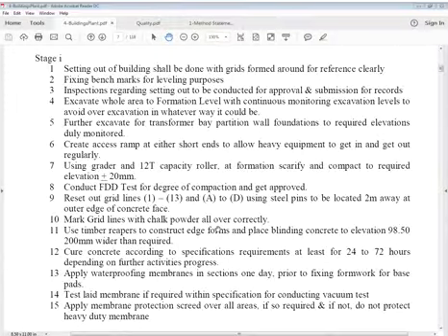Whatever reading you get on your leveling staff, you can say this 0 plus this reading is called height of instrument, and then you can deduct other points from there. After height of instrument is obtained, you can take other levels, wherever you can say reduced level. Here reduced level was 0, reduced level plus reading of staff is called height of instrument. You want to establish other levels or check other levels, you can check them, you can establish them.